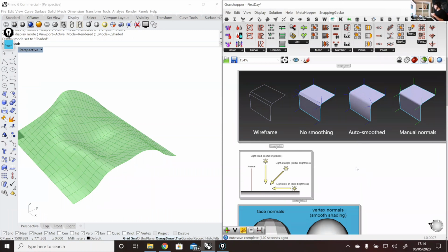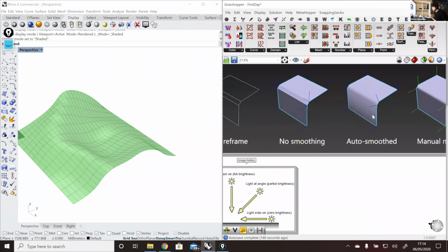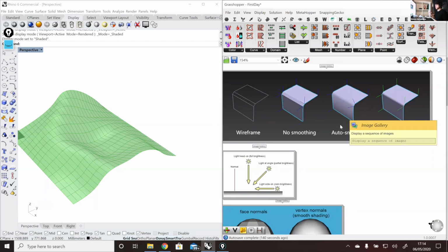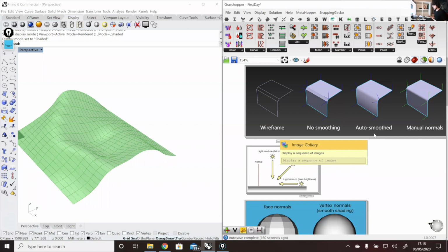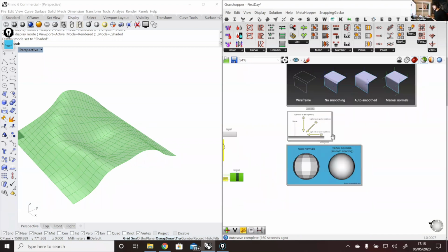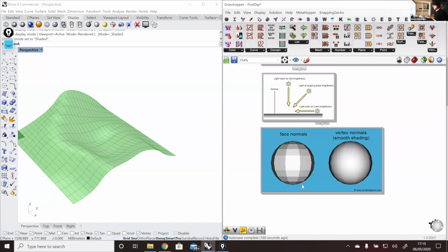So in this case, for example, I'm simulating this smoothness with this welding instead of creating a more detailed mesh. Because you could start to create a very detailed mesh so that it looks smooth, but with this solution, you can actually fake this smoothness. And by doing that, you can also help in the optimization of your online application. And that's the difference between having something that is completely not welded and something completely welded on the other side that is completely smooth.